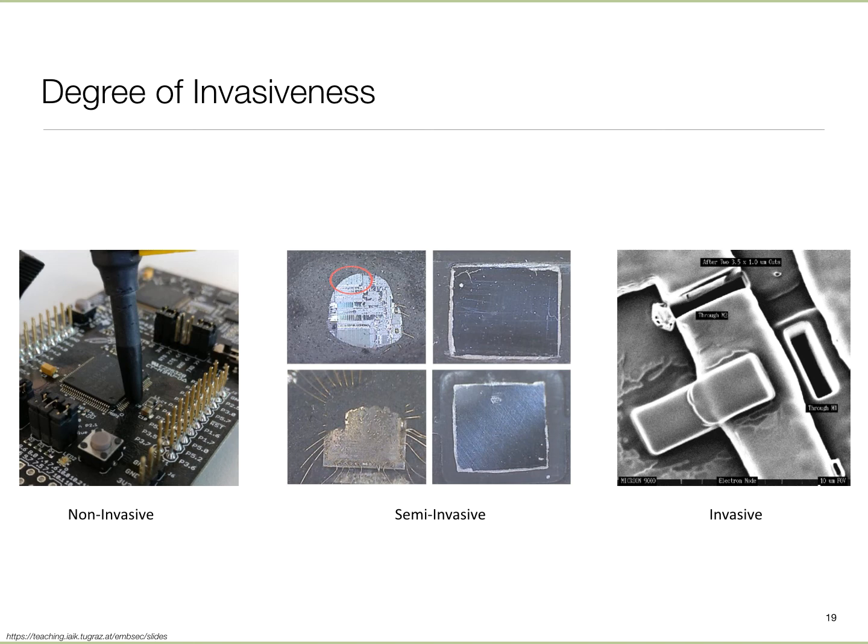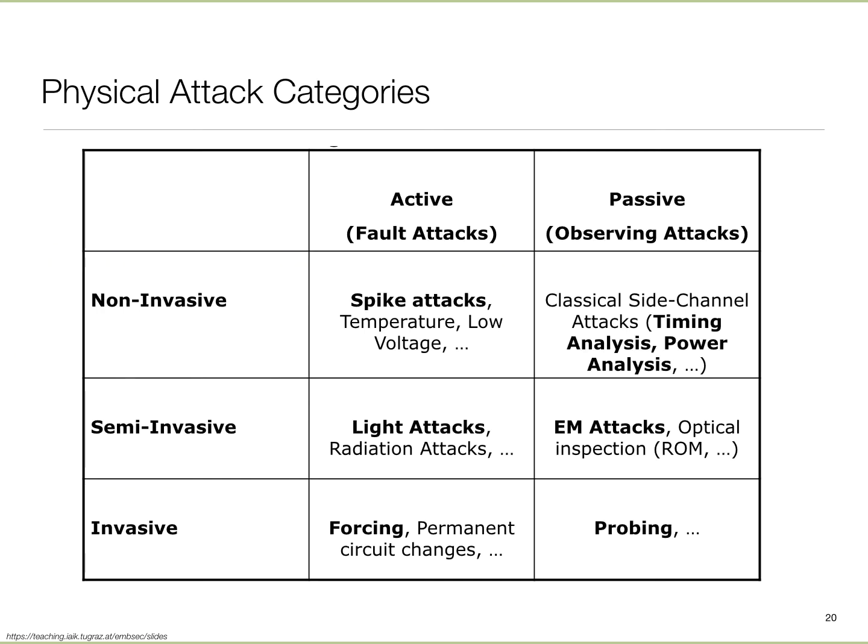Again, the simplest one is power, right? Your system operates on a battery or USB power supply. You can just put a $10 little board, or even a cheaper one, which basically measures how much power the system is consuming, and then just capture it on an oscilloscope or something and analyze it. So that's the simplest case to all these sophisticated ones.